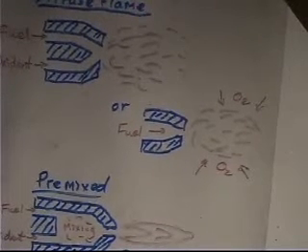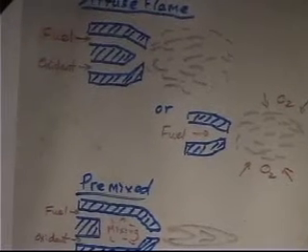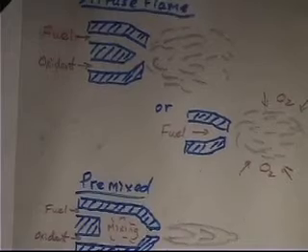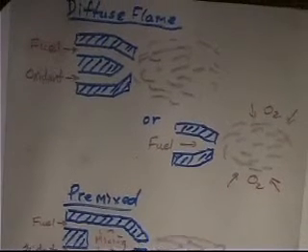If I go back to these three things and I wanted to look at heat intensities, a diffuse flame, typically burning in air, but even if you had one burning in oxygen, a diffuse flame will give you something on the order of 1 to 30 watts per square centimeter. Sometimes less, sometimes a little bit more, depending on the diffuse flame. But a candle is like 1 watt per square centimeter. I mean, you can put your finger through a candle at a nice slow rate and not burn yourself. Not too slow a rate, but you're not going to burn yourself.